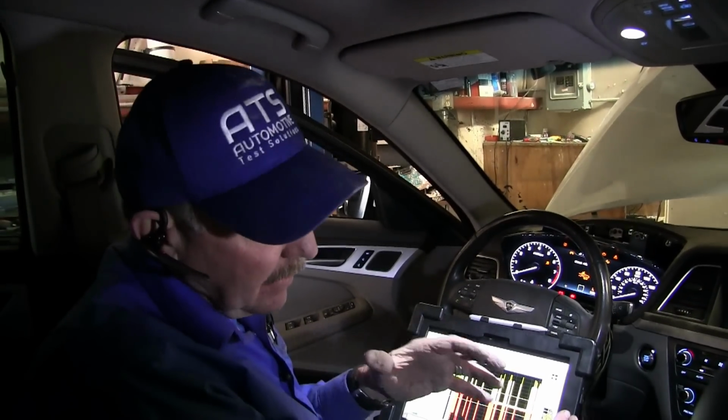And when the shop pulls down the subframe and the rear end where we have access to that piece, they're going to need to check the powers and grounds to make sure that the module has proper current, because the module can't work without current. Once the power and ground are good, they're going to need to put the module in, and then this vehicle is going to be ready to return to the customer.